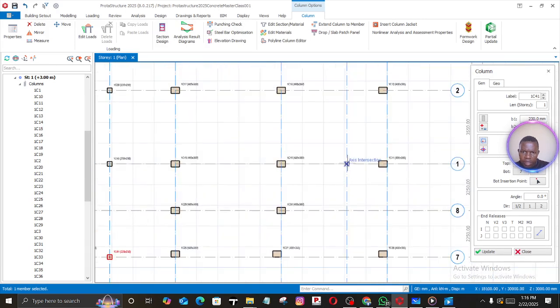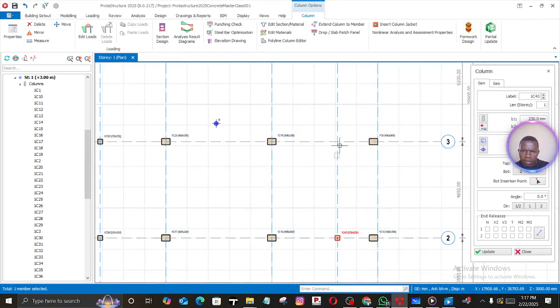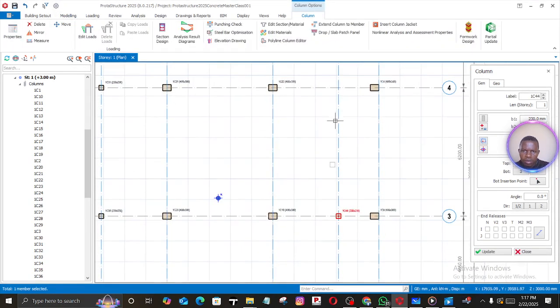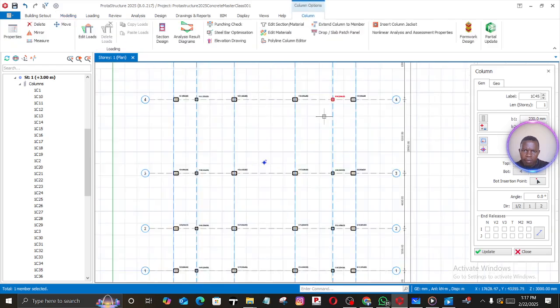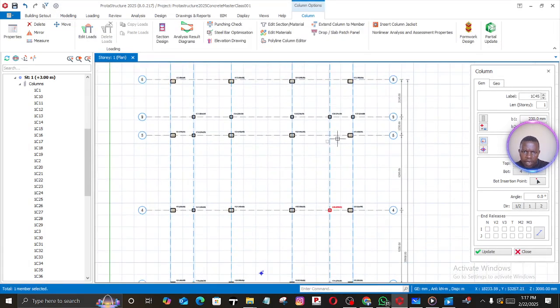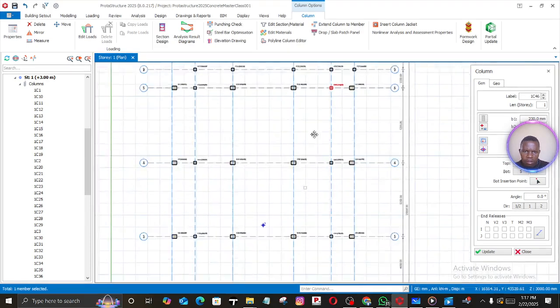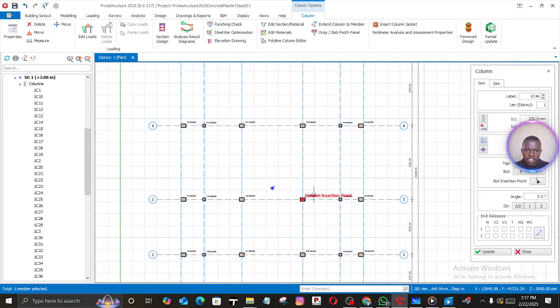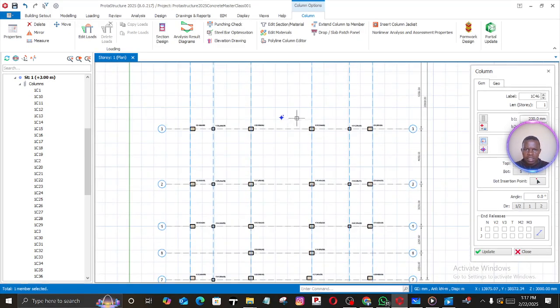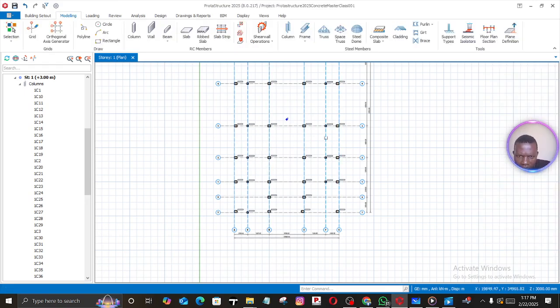So we also need maybe another beam here. We also need another column here. Not a beam, but a column, sorry. We also need another column here. We need another column, so we have this. This one can be able to sustain it, yes. To take care of our wall, we'll be having a shear wall here. And if need be, we may consider adding an extra column here.